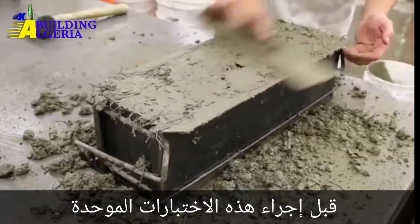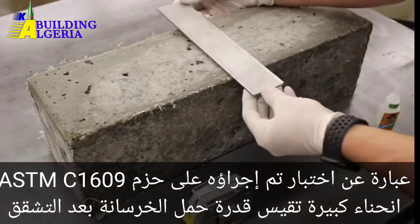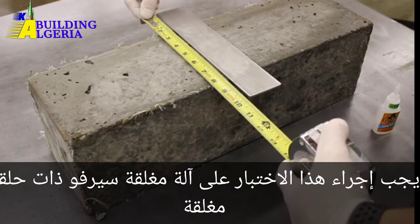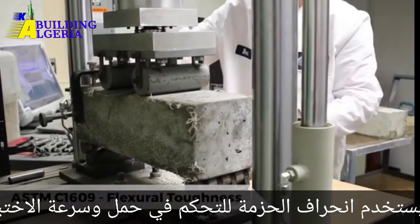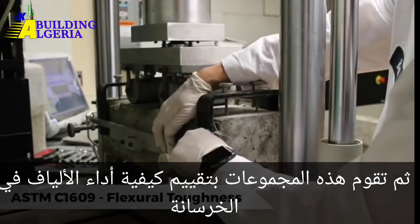ASTM C1609 is a test conducted on large flexural beams that measure the post-crack load carrying capacity of concrete. This test must be conducted on a closed-loop servo-controlled machine that uses the deflection of the beam to control the load and speed of the test. These tests then evaluate how fibers perform in concrete.